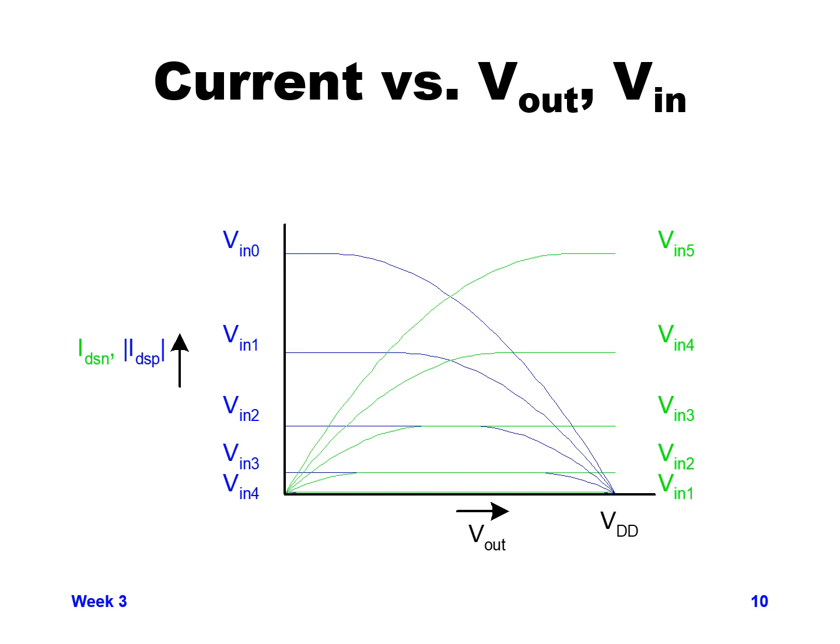So here, if we assume that the VN values, VN 1, 2, 3, 4, and 5, and VN 0 in the case of the blue curves, are if VN is that many volts, and assuming our VDD is 5 volts, just as an example, this is the type of curves we would get. So for an NMOS device, there's no VN 0, because if you had the input equal to 0, you're in cutoff and you get 0 volts out, and so there's no graph for that.